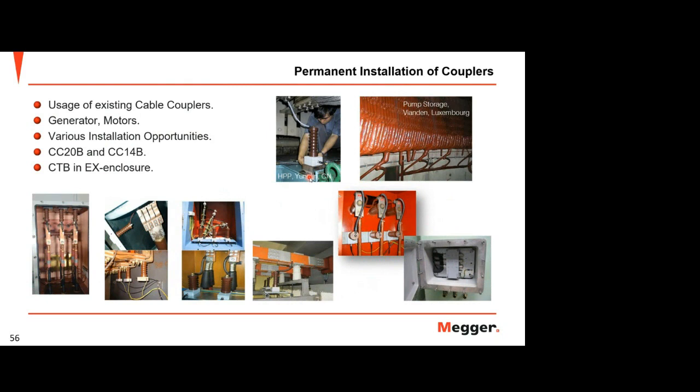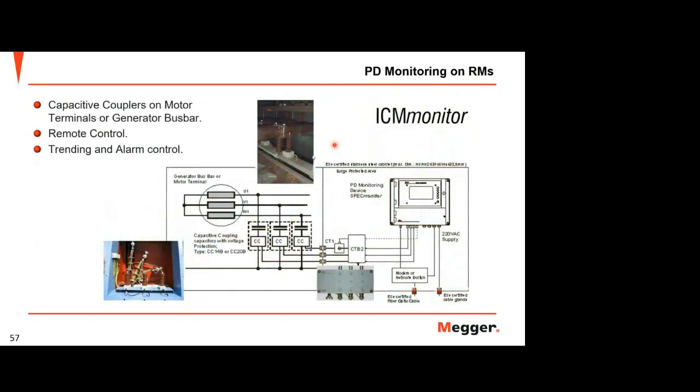either permanently, continuously, or you can do monitoring at a certain time, maybe only 1 week or maybe 10 days, just to capture the partial discharge phenomena in your rotating machine. This is a general connection, not only our product, all products will have the same connection.